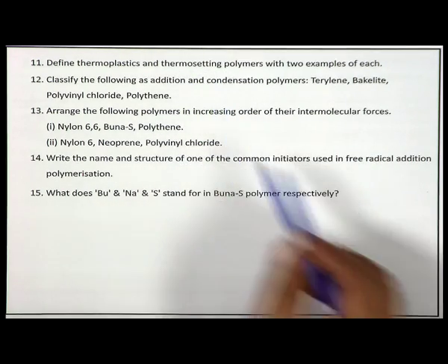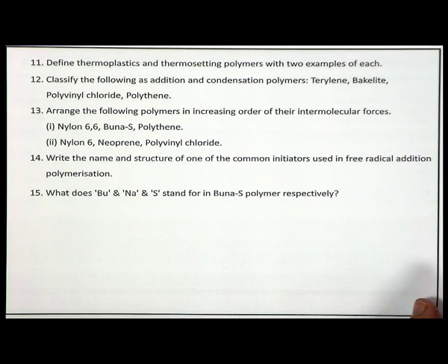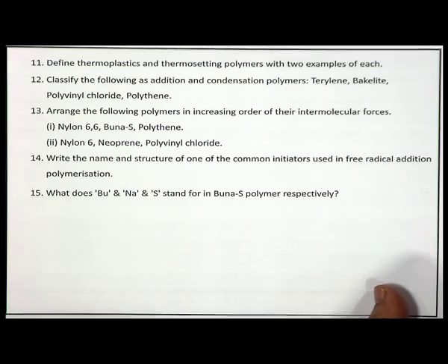Whereas, in case of thermosetting polymers, you basically make an uncrosslinked polymer and then heat it, and it will cross link on heating, and once it cross links, you cannot now recycle or infuse it again.